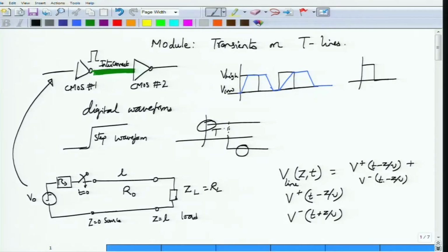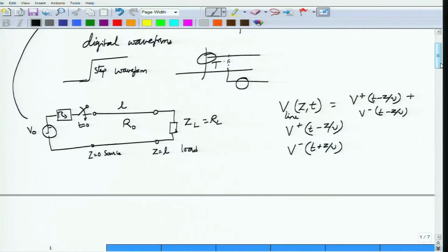What is this v here? v is the phase velocity. Let us not get into the reason why this is called the phase velocity and whether this is the same as the one that we defined earlier. We will defer all those discussions to some time later. What we want to show is that this v is related to L, because the delay of the transmission line is given by L by v. v can itself be written as c by square root of epsilon r. So if the transmission line is filled with insulating material that is not air, then you have to calculate the velocity of light on the transmission line, and that would be c by square root of epsilon r. So the basic idea here is, imagine that there is a length here.